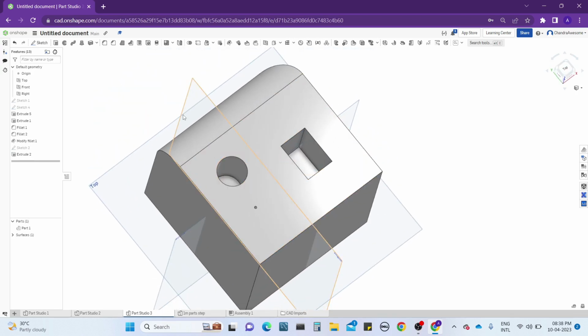Now I want to cover these faces, which means I want the same as the previous one. For that you need to apply the delete face tool with heal and cap. Let's work with the cap for now.